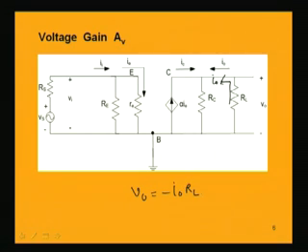Now, again, what is I naught? I naught is nothing but that part of the current which flows through this resistance RL, coming from the independent source alpha Ie, because we see here alpha Ie is divided into two parts, one going through RC and one going through RL. So, the part of the current which goes through RL is basically alpha Ie into RC by RC plus RL, but the direction is opposite to I naught.